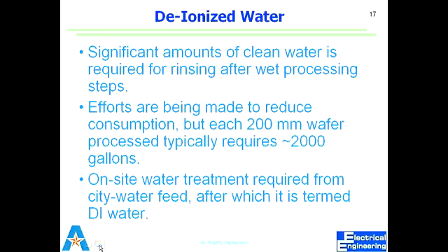And water is one very important agent that we use for cleaning. But water itself is not clean as such. We have to clean it. We have to deionize it. What are the things in water that can be a problem for processing? Of course, ions. Deionize means you want to get rid of ions. What else can be there in water? Salts? Yeah, deionization, salts become ionized. It can have particles, organic particles.